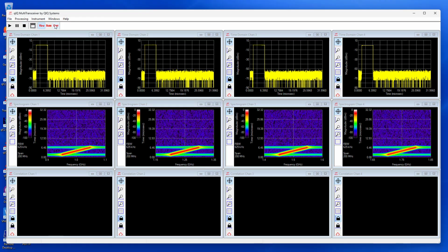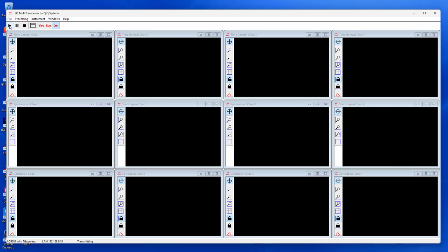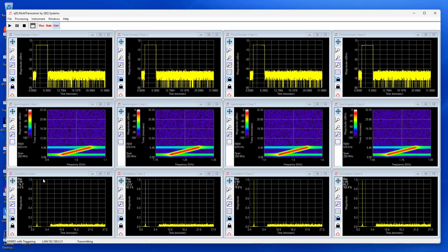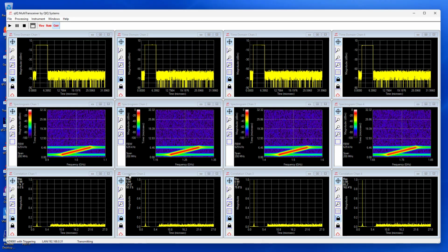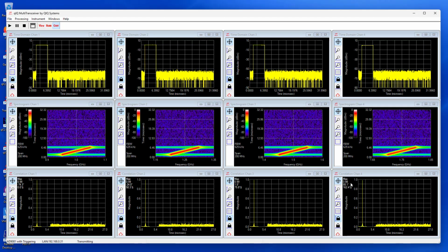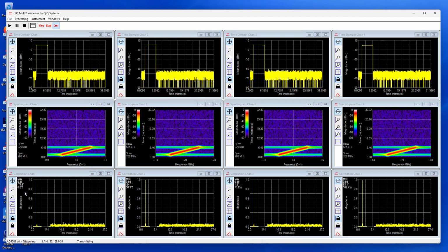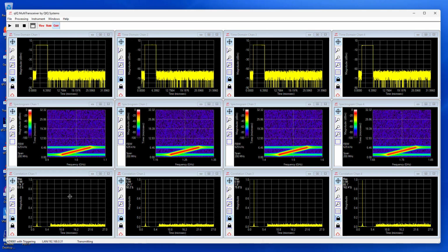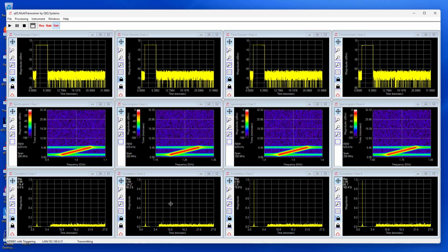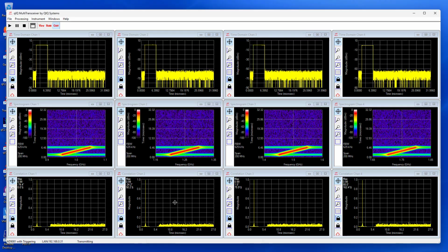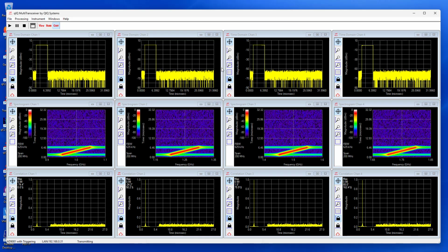I'm going to turn on the correlating receiver, and we'll run that so you can see the peak of the correlation here happening at the beginning of our chirp signal. And notice the stability of that correlation. These things are lock solid. They are not changing at all in phase relationship to each other. That was normal. We saw that with the 9084. But in this case, we've got all of these acquisitions now that are timed up just right.